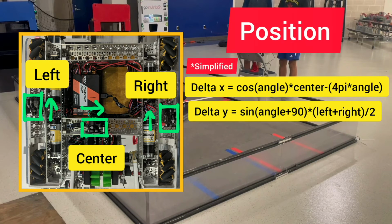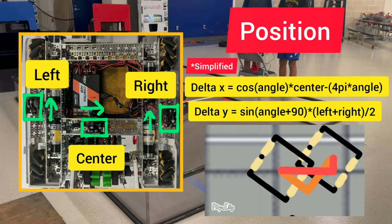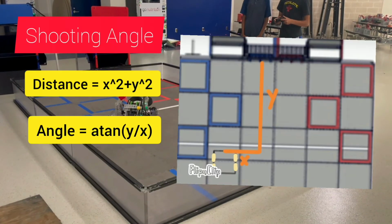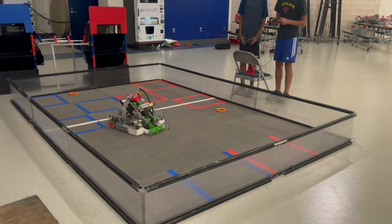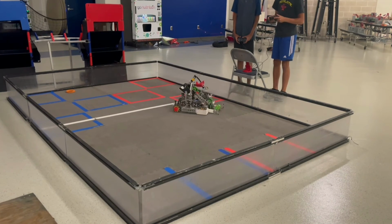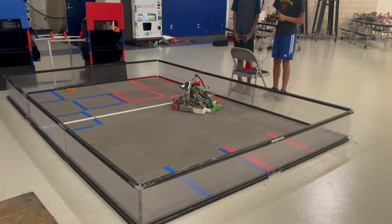We also use the horizontal and vertical wheels to find vectors along the x and y axis of the robot. After converting it to the frame of reference of the field using the angle, we are able to find the robot's displacement. A function then calculates the necessary angle to shoot based on our position. We also plotted out various RPMs and created a linear function based on distance.